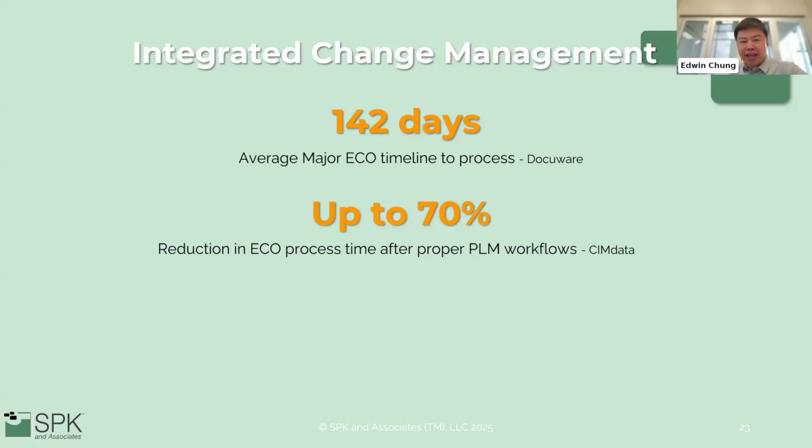Windchill handles the mechanics of it, the conductor, so to speak: where-used analysis to see every BOM it touches, effectivity dates so the right units change at the right time, role-based approvals. We haven't talked about roles. We'll talk about it soon. And automatic notifications, right? The tasks are there so that every single day I come into work and I see, hey, these are the ECOs that are waiting for my review and approval.